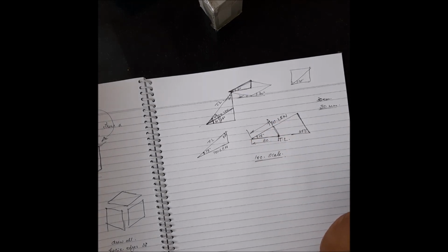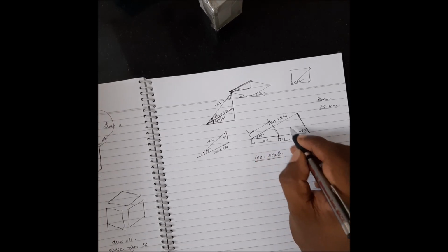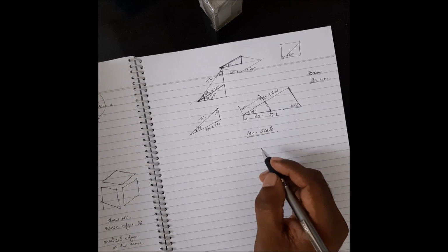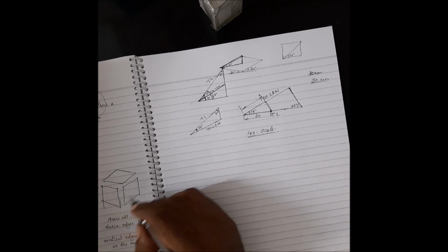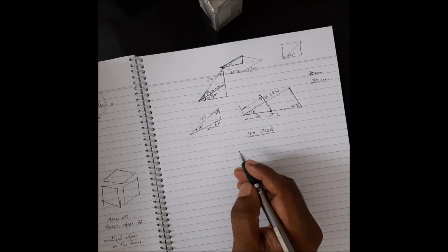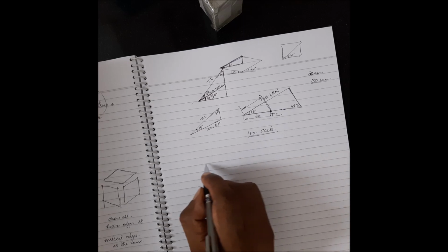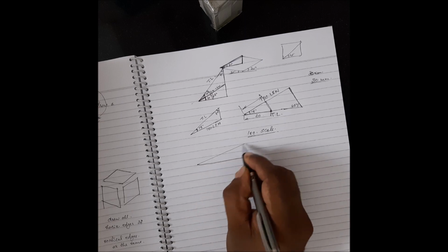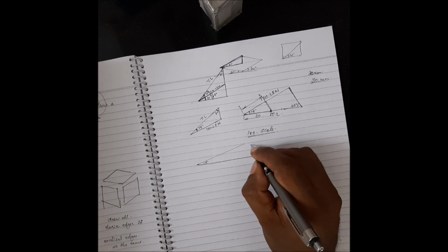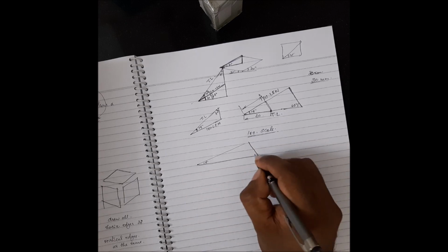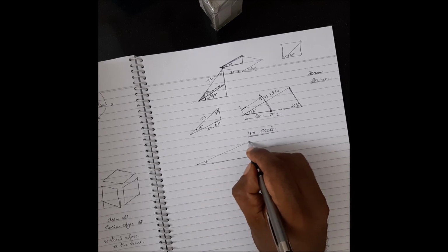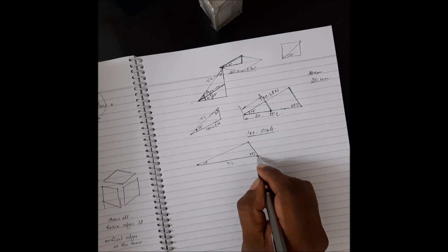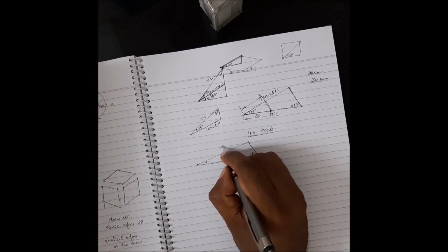All right, now you can make any measurements here and find out the corresponding isometric length using the scale. If you have a very large measurement, or let's say 5 or 10 measurements to take, you draw a longer line, and from one side you take a 15 degrees angle, draw a line, and the other side you take a 45 degrees angle. The length of the line you can decide, it doesn't matter. So what you have constructed here is a scale. This side is the true length of the line and this is its corresponding isometric length.